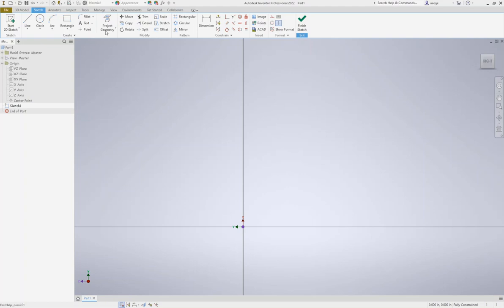So I'm going to go with the line command and start a brand new line. This is going to be the center of the engine, hopefully, bottom at least. We're going to move to the left about 3.1 inches. So I'm typing 3.1, enter. Now we need to go up, and the length of the line is already highlighted. It's 1.57. Enter.